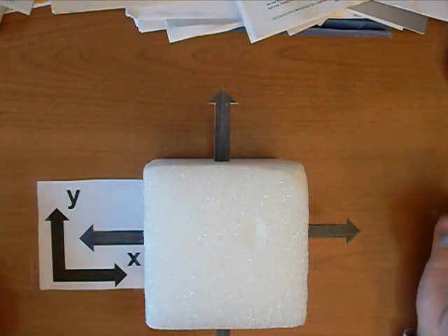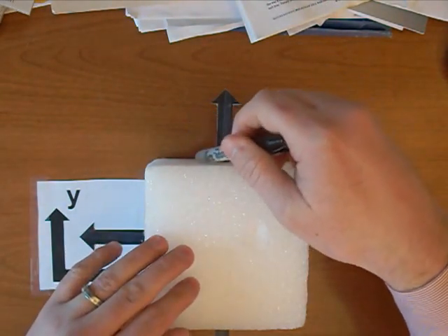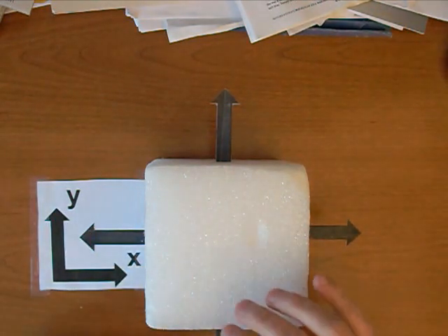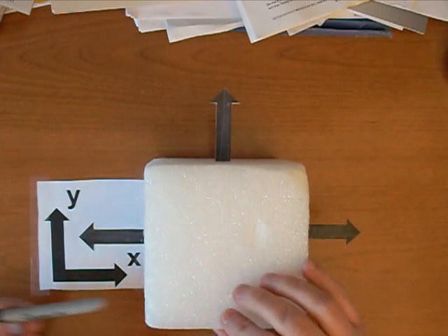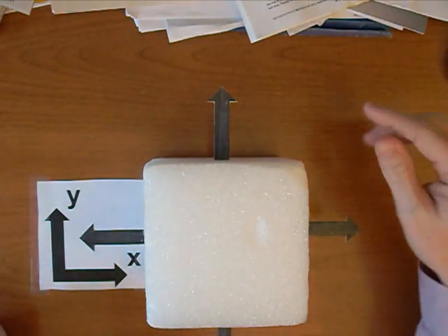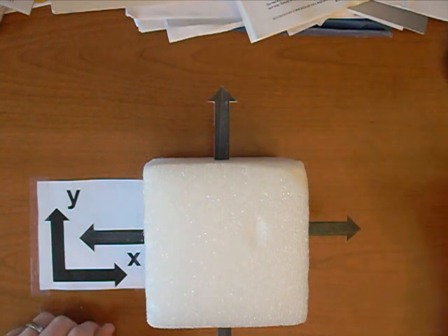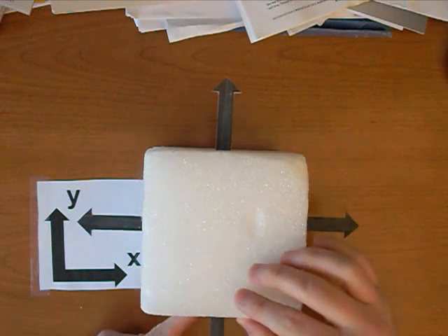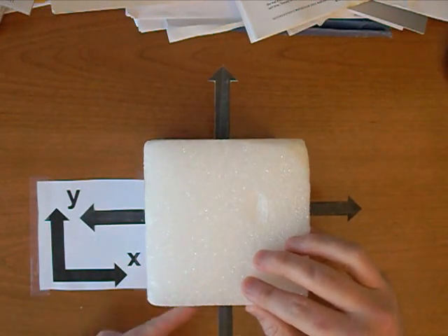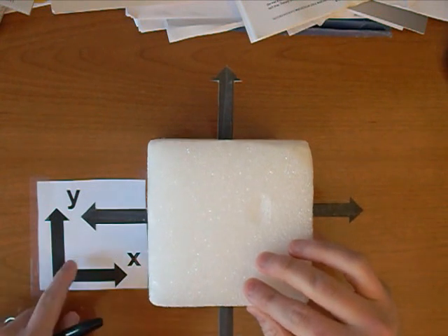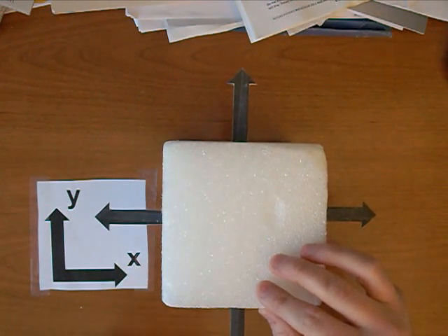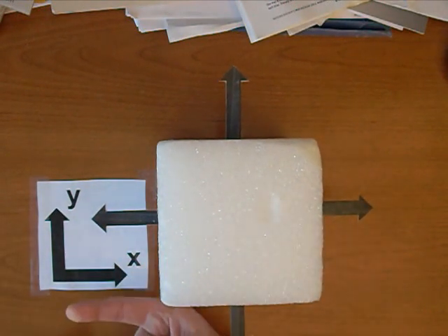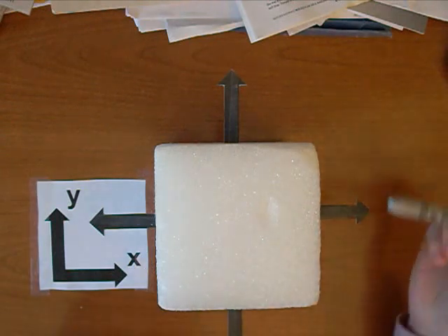So that's our pressures. For our shear stresses, which act on this face right here and this one right here, if you remember in the drawing, the shear stress acting on this bottom face is pointing in this direction, and on the top face is pointing in the other direction. The reason is that on this face, the unit outward normal is pointing in the negative y direction, as you see from our coordinate system. So therefore the shear stress is going to point on this face in the negative x direction, this way. And then vice versa on the top face.